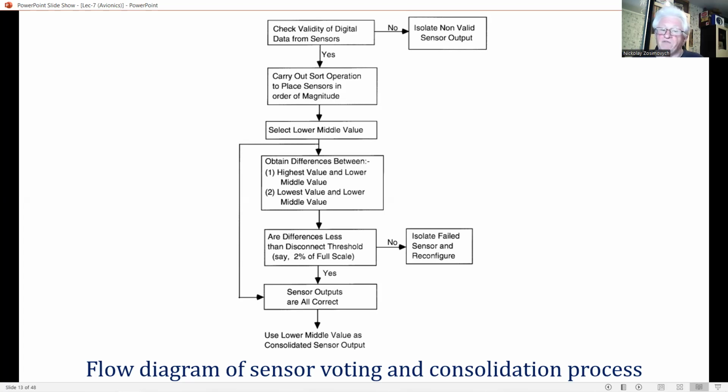Other tasks include automatic limiting of the pilot's input commands to achieve carefree maneuvering, to restrict the pilot from attempting to maneuver the aircraft into an unacceptable attitude or approach near the stall or exceed the structural limits of the aircraft; changing the control laws to maintain effective control in the event of sensor failure; or control of the secondary control surfaces, leading edge flaps, slats, trailing edge flaps, and spoilers; and control of engine thrust and possibly thrust vectoring.